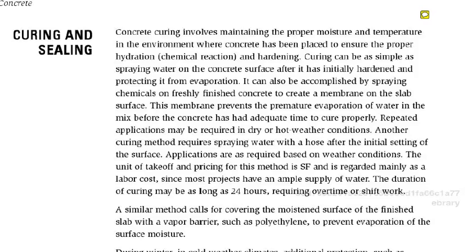The curing compound, anyway, forms a membrane over the concrete, and the membrane helps slow down the evaporation of water in the concrete so that it has time to hydrate and cure for you. So it's a real important step to have. You also can spray down concrete again after it's been allowed to cure up, and you don't have to worry about washing away the fines on top. But you need some type of material to cure it.